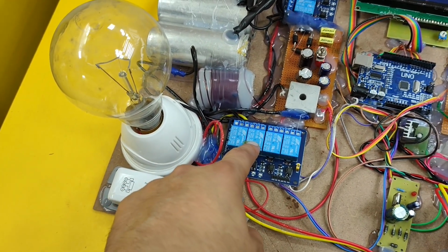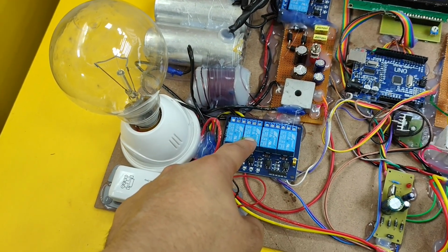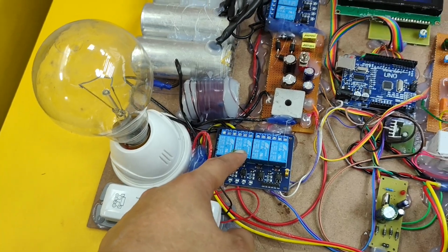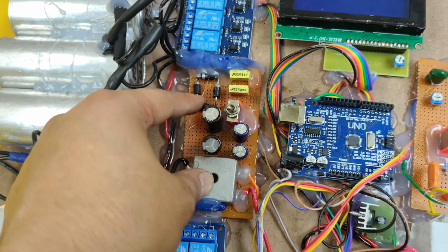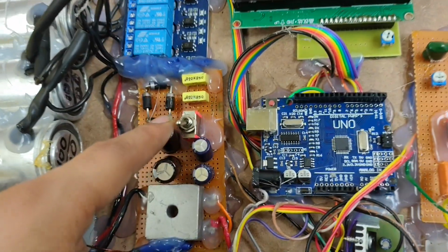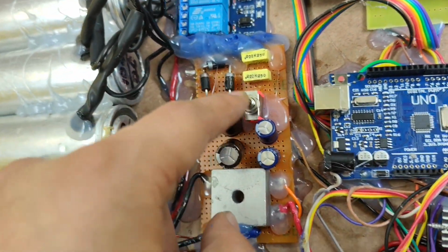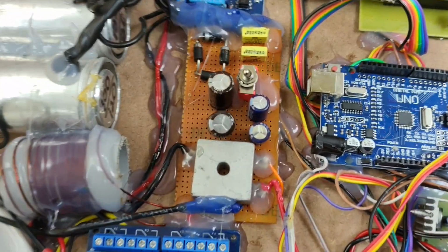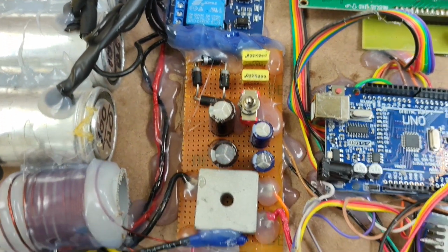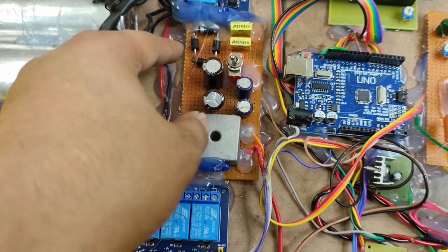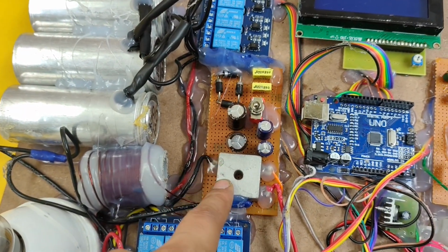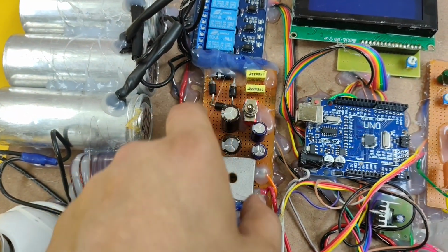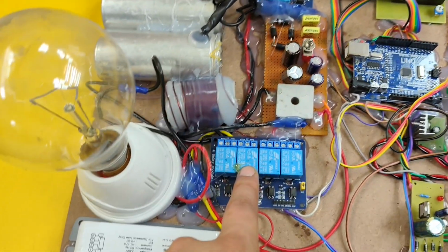The second relay will add the harmonic distortion hardware, meaning a non-linear load. So this is the non-linear load, and you can select this load with the help of this toggle. This is the second toggle. With the help of this you can select this harmonic noise, or you can say THD, total harmonic distortion hardware. So it is a non-linear load, and it will deform the waveform, right? So this hardware is selected with the help of this second relay.